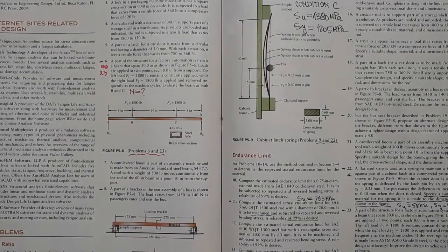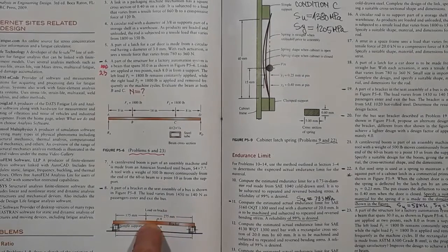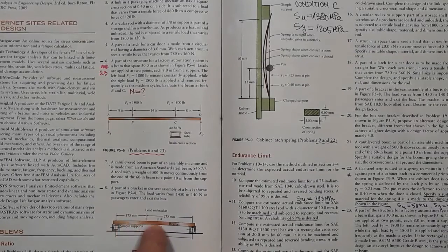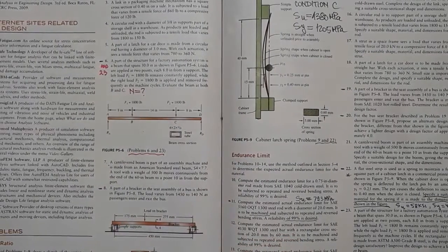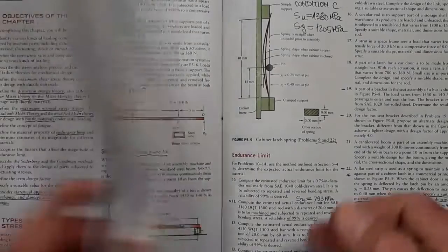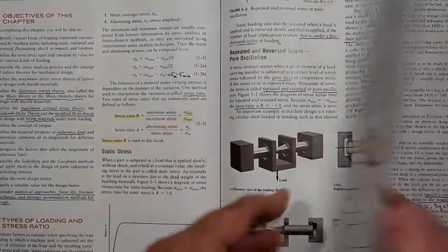beam. It's flat, width 60 millimeter by 12, and it's loaded 175 millimeter from one end. Full length is 450 millimeters, with a load that varies from 1450 to 140 newtons. And we need to calculate the stress ratio R, minimum stress over maximum stress,